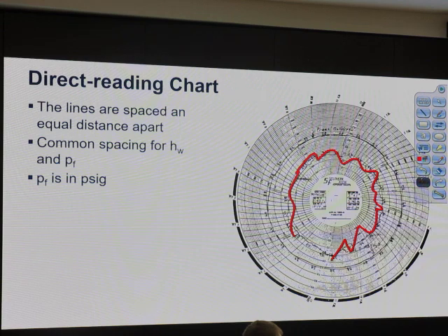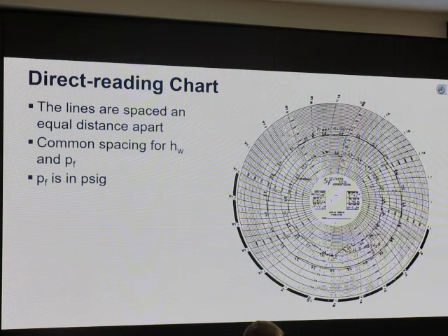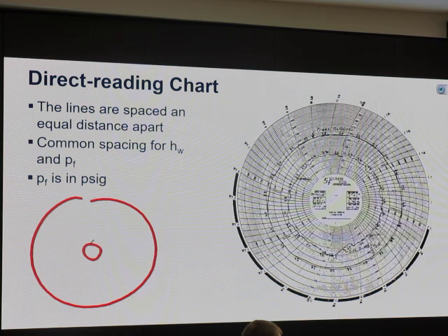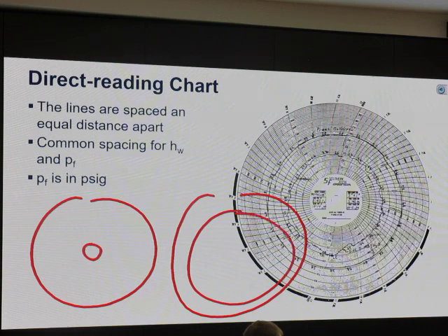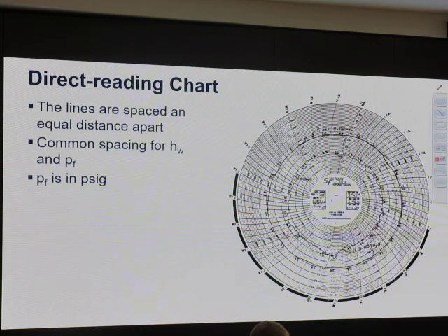Rule of thumb to select the orifice plate. How big should the orifice plate size be? My answer is that the hole size should allow a pressure drop in inches of water of about 20 to 80% of the reading. In this particular case, the reading for the pressure drop, HW, in inches of water is from 0 to 100.